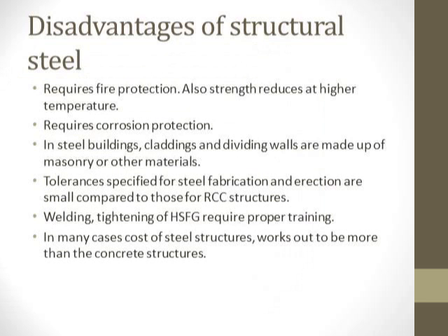In steel buildings, the claddings and dividing walls are made of masonry or other materials, and tolerances specified for steel fabrication and erection are small compared to those of RCC structures. Welding and tightening of high strength friction grip bolts also require proper training. In many cases, the cost of steel structures works out to be more than concrete structures. So these are some of the advantages and disadvantages which have to be known.